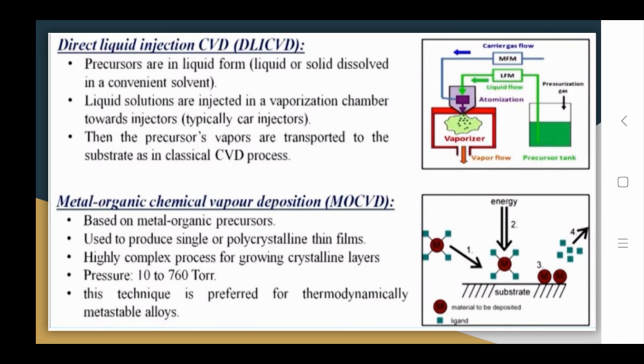We have pressurized precursor tanks where we apply gas pressure. Due to that pressure, the liquid goes directly into the atomization process, generally through an atomizer. There we apply high pressure air, due to which the liquid forms small bubbles, and then they come out directly as vapor and are deposited onto a metal surface, and the rest of the vapor goes throughout the chamber.